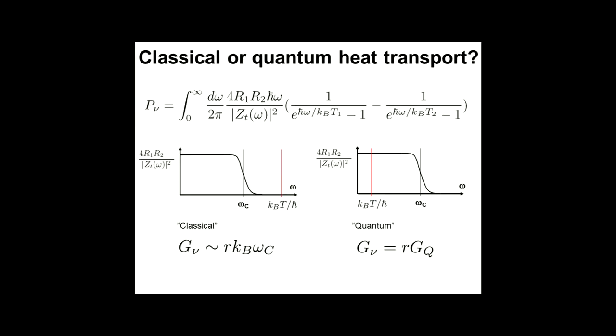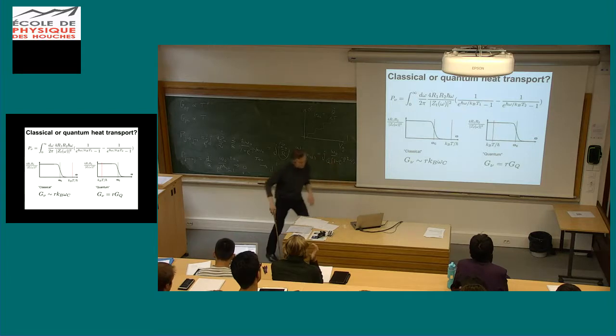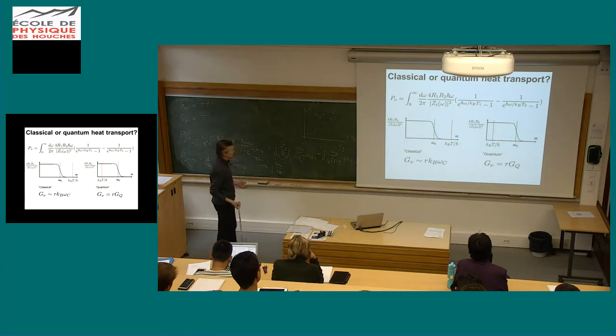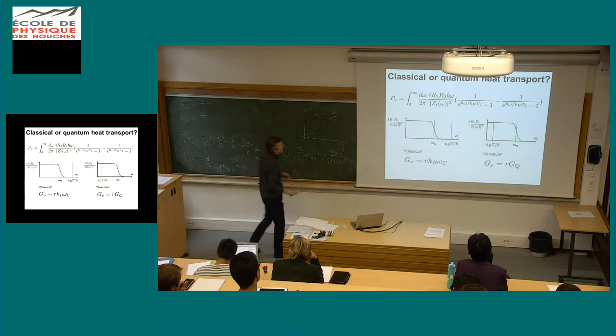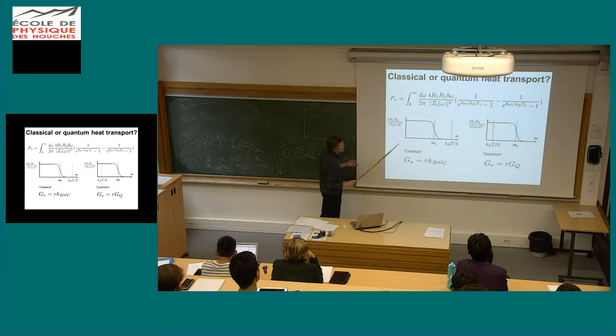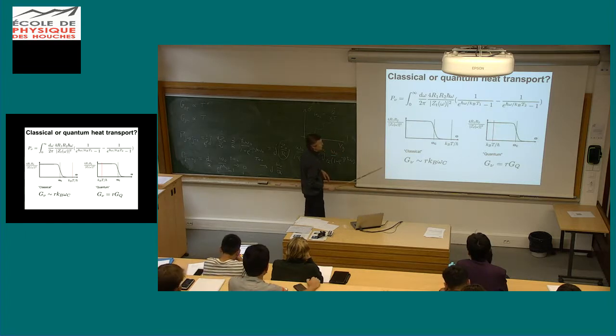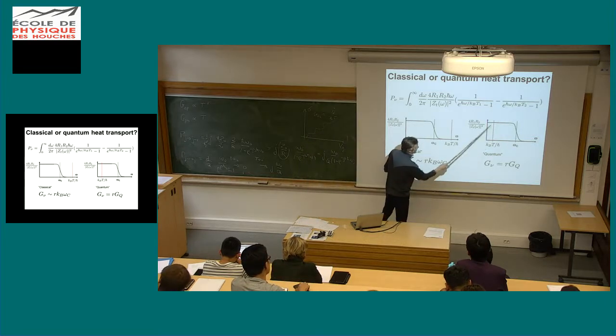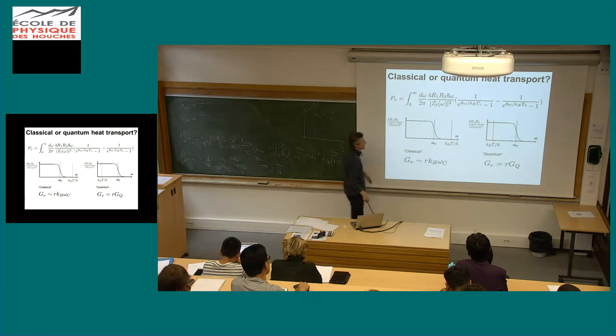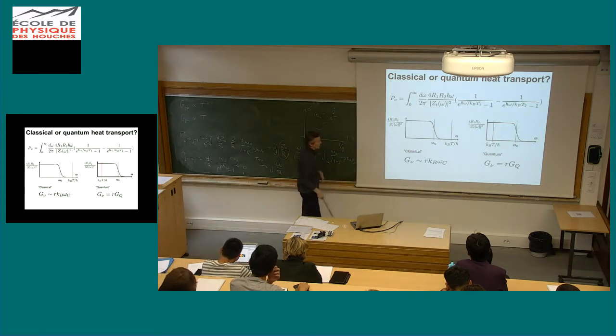Okay, so maybe just very briefly, one may ask the question, when is this important? Of course this is important when the matching is good, but you can't reach this at, say, high temperatures, because the important thing is that you have some thermal noise, and all this noise has to be transmitted from one resistor to the other. So you have to have the condition that the thermal frequencies are much lower than the circuit cutoff frequencies. If the opposite occurs, then you of course don't reach this.